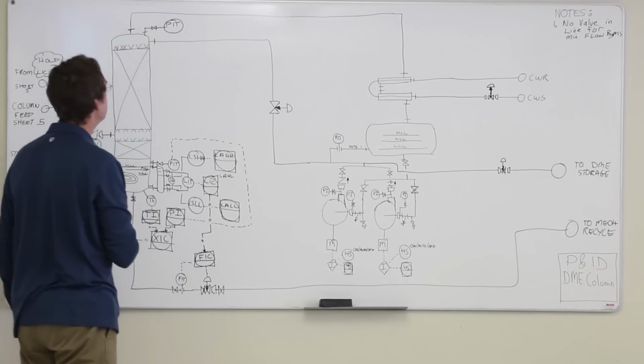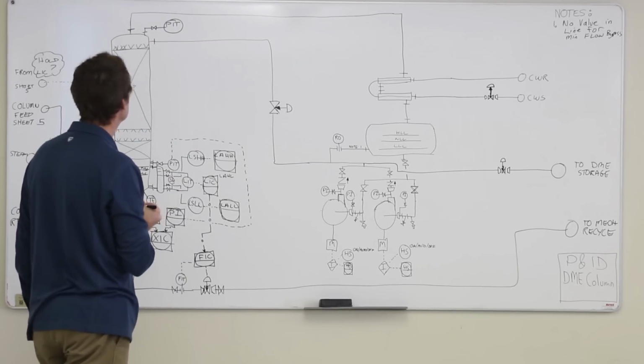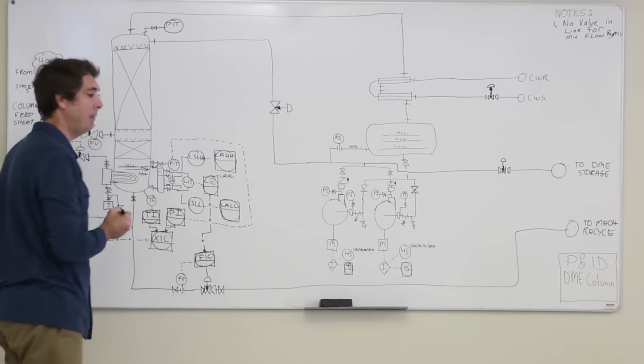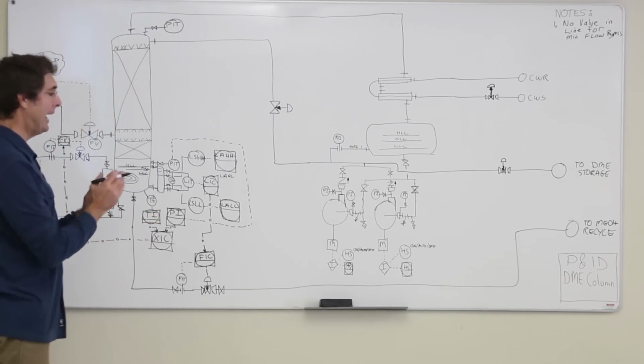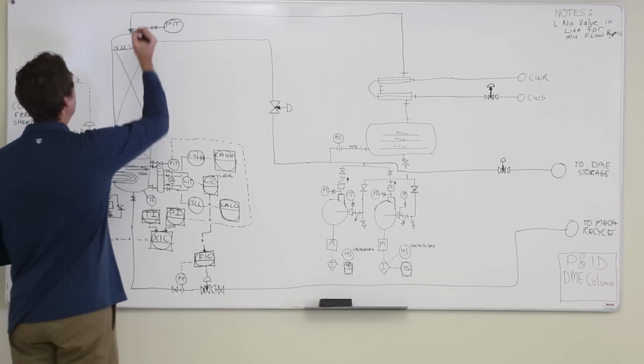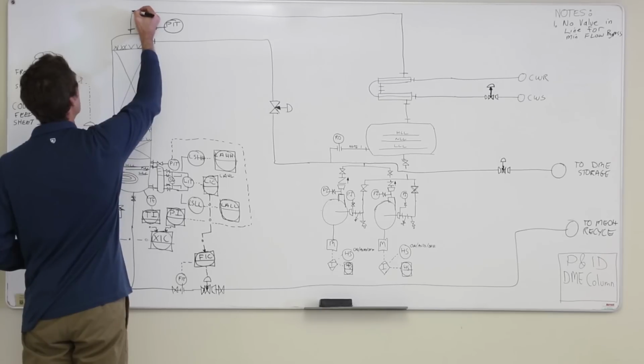Like that. We need to measure the temperature. The best way to measure the temperature is to have the flow of the fluid basically impinging on the temperature element. So the best way to do that is put the temperature element right in the elbow of the piping.